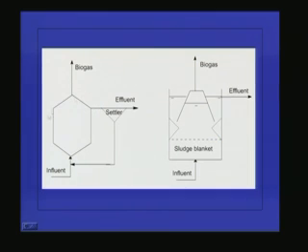Because of this biogas production, the entire reactor gets mixed thoroughly. If the mixing is not proper, we can provide mixing externally also. So definitely, whatever the biomass concentration inside the system, the same concentration will come out along with the effluent. So here we collect the effluent and allow it to settle. This is a settler or a sedimentation tank. All the biomass coming along with the effluent gets settled, and is recycled to the system along with the influent.